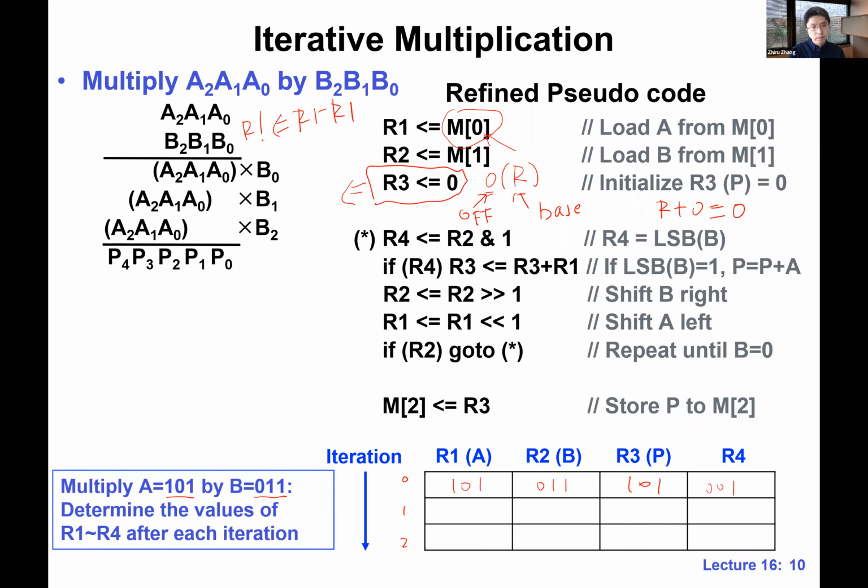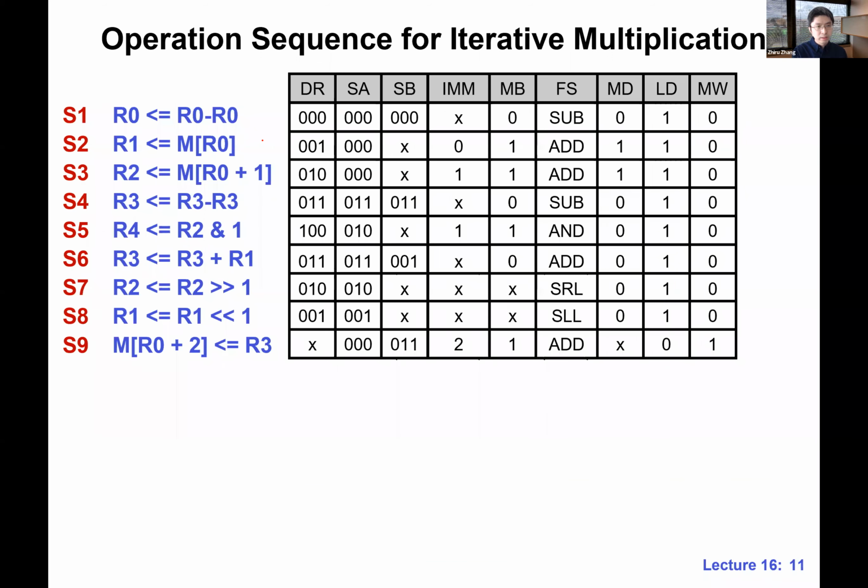Okay. Is it clear, guys? And this is our instruction set, right? Basically, we don't really have an instruction that assigns 0 to the register. So that's why we are doing a subtraction. Jacob also made a very good point, right? Once we have a 0, then we add, so we basically use that register as a base address. All right, it's not too clear. Okay, and this is the complete instruction sequence. Actually, the answer is already in the next line, right? That's how we make a 0.